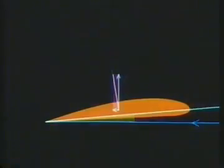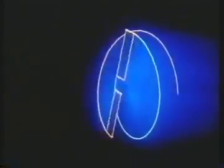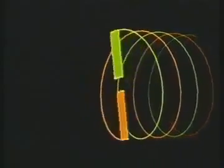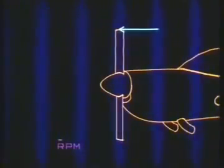In very simple terms, a propeller or air screw is really two or more rotating aerofoils set to pull the propeller through the air, in the same way as the thread of a screw pulls it into wood. During flight, its motion will comprise rotational velocity and forward velocity. With the propeller stationary, any forward velocity is that of the aircraft, the true airspeed.